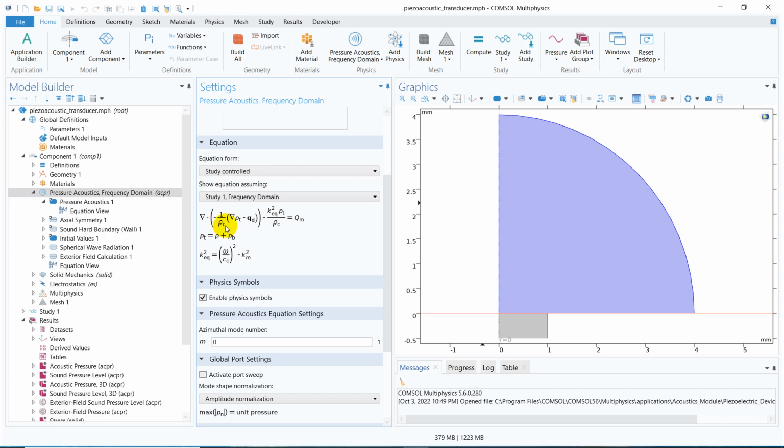Here, initially you can see there are a few coefficients like rho c, this is the density. You have Pt, that is the acoustic pressure, and again Pt is taken as P plus Pb, so there might be a background pressure as well, and if it is so, then you have to add it up, and this is the original acoustic pressure, maybe coming from your source. Say you have a device and the device is vibrating, it is generating a kind of acoustic pressure.